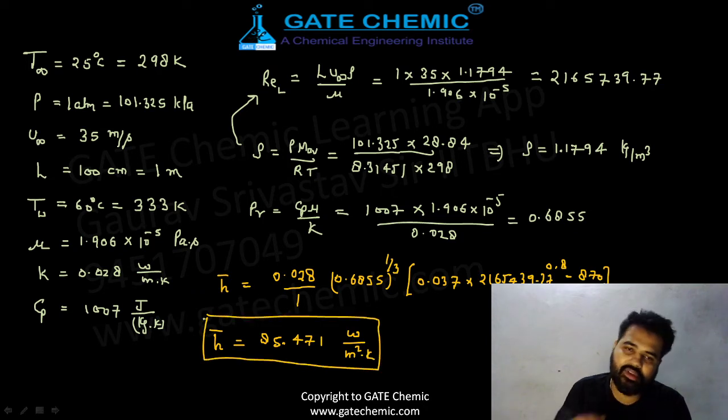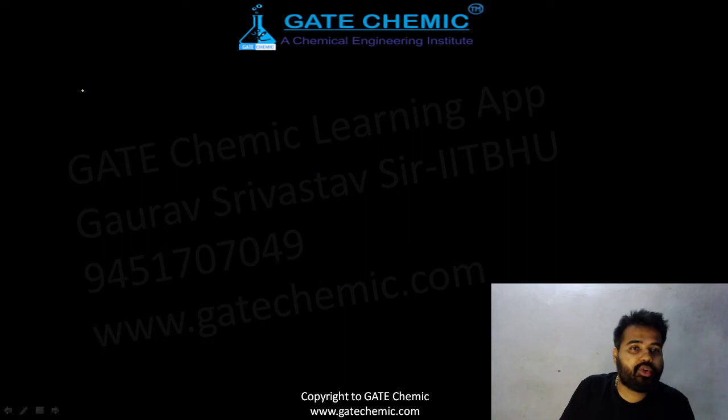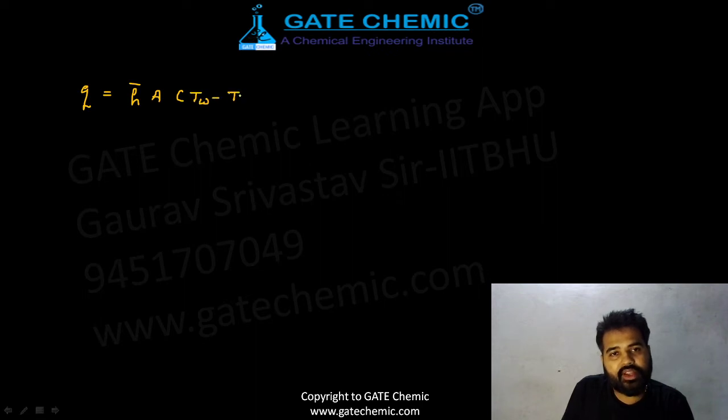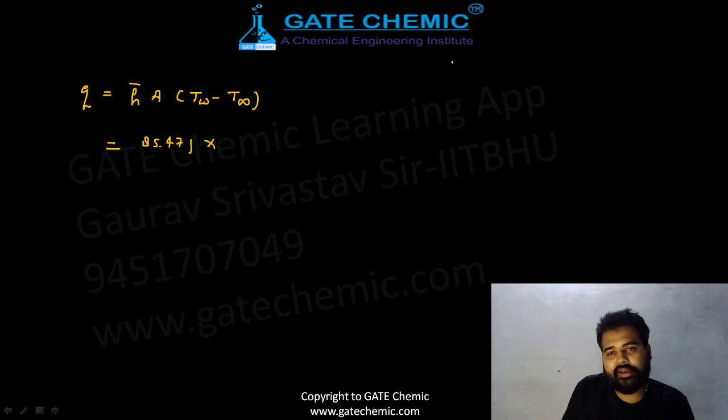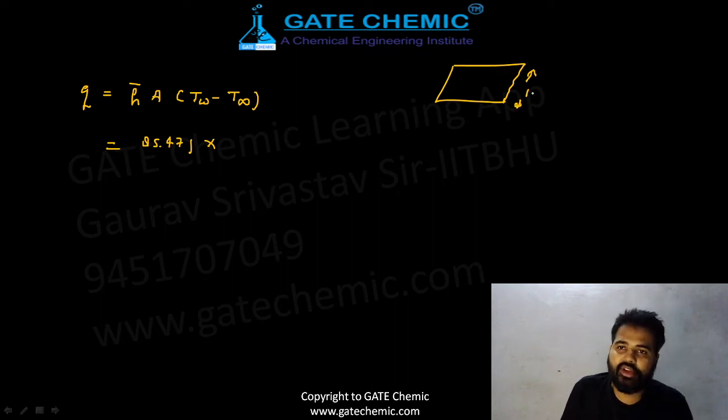Once you got h bar, then you will get your answer, because Q can be written as h bar into A into Tw minus T infinite. So this h bar is 85.471. Now what is the area, beta? If this is your flat plate, it is written that in Z direction take unit width, that means 1 meter, and its length is 1 meter, that means 1 into 1 will give its area.